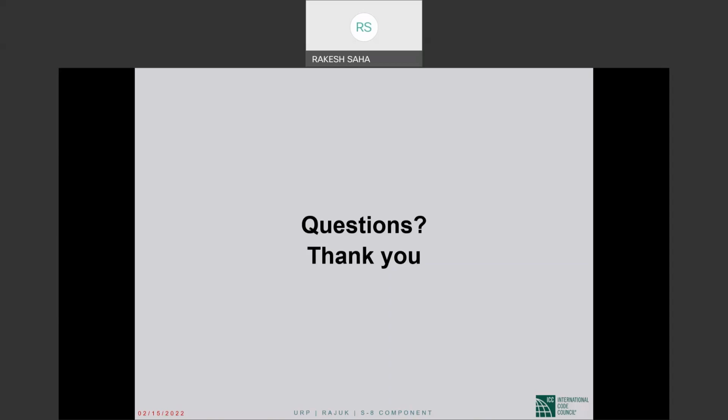So it is not that you need to check drift to figure out whether to do static analysis or modal response spectrum. It is the other way around. You make a decision that your design shall be based on modal response spectrum analysis, probably because you have a tall structure and an irregular structure. And then you will have to do the drift check as always, and you will also have to account for torsional irregularities if there are any.